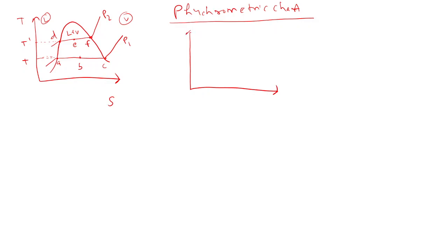So this is the TS diagram. Now the same thing I want to draw in the PT diagram. In TS and PV, the two phase region is like a dome, all curves. In PT, how will the two phase region show? Anyone knows? It is absent. The two phase region is absent in PT. It would be one simple line, right? This way. Is it clear to all?